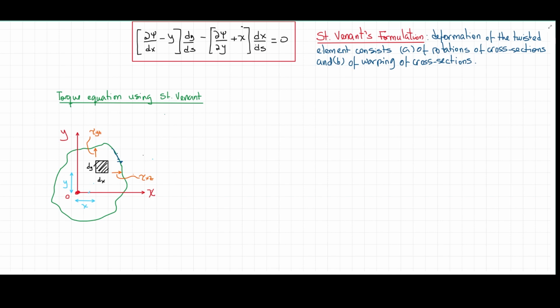Then I'm going to have a differential torque produced by those shear stresses. For example, in the first case, it's going to be this torque here, that is, the shear stress tau yz acting on a differential area. That's going to give me a force, and that's going to be multiplied by a distance x,